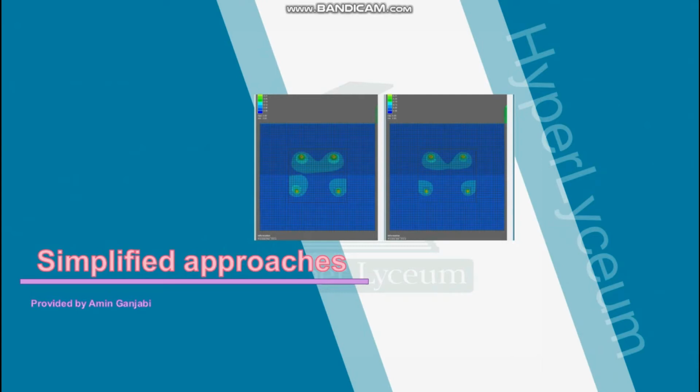This video is about simplified approach. Simplified approaches are used to decrease the simulation time. But be aware that this also decreases the result accuracy. For different process types, Simufact.welding offers different approaches to reduce the simulation time, like neglection of welding sequence, decoupling of model, or linear material models.